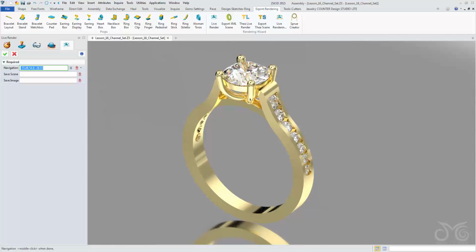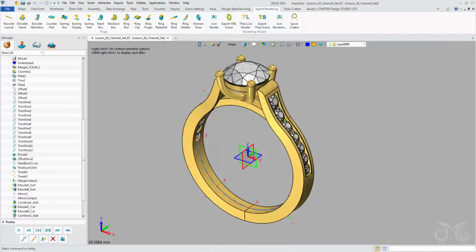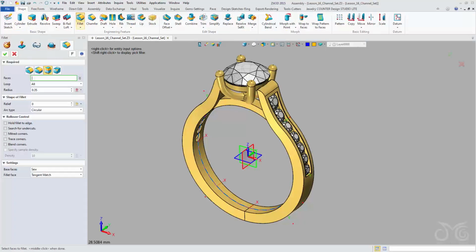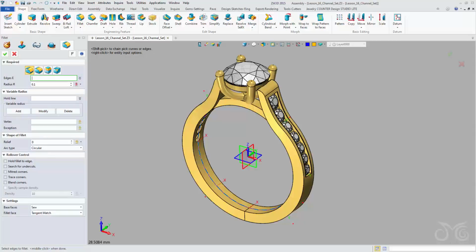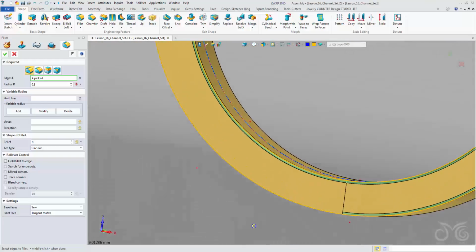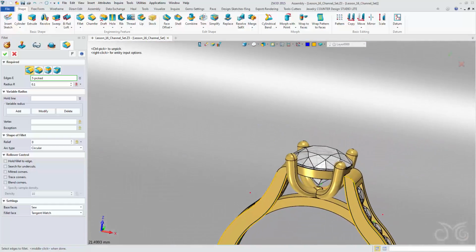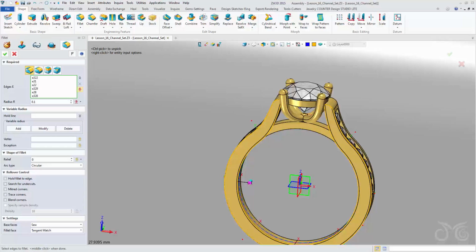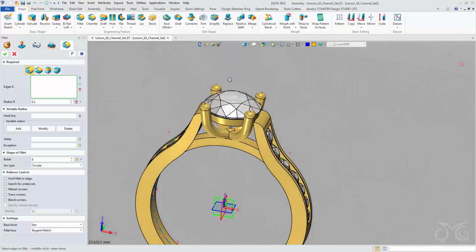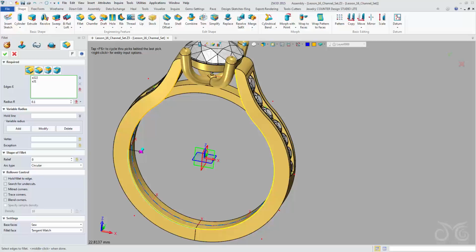Okay, you can see how some of these edges are a bit harsh and abrupt. To soften these up in the live renderer, I like to add in a small fillet. Just a small one. Edge fillet 0.1. Just on our edges here. Okay, it's not grabbing that one. To unpick all, let's do these edges.